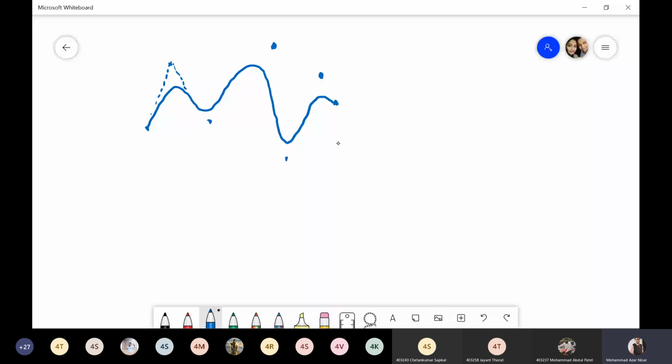So the advantage of a B-spline curve is that it is independent of the number of control points, as compared to the four control points used in cubic Bezier curves. And in the case of B-spline curves, we can generate a linear, quadratic, or a cubic curve.